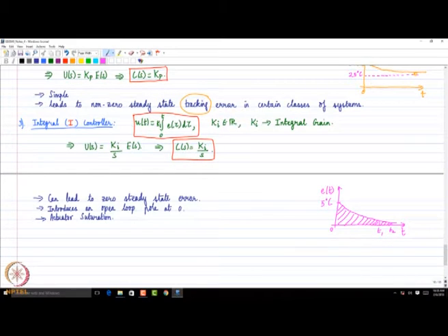Anyway, when we do control design, we will do all these things. Not only are we interested in making sure the error goes to 0, but also in ensuring that the control input we are giving to the system is within practical bounds. Otherwise, there is no point. For example, if I want a linear motion system in some machining assembly, and I purchase an electromechanical motor based actuator which can provide a maximum of 100 newtons, and I program a controller which at an instant asks for 1000 newtons, I can't realize it in practice. Then I reach actuator saturation.